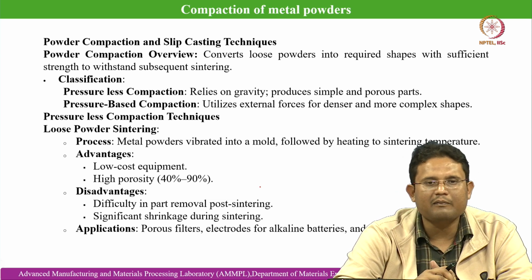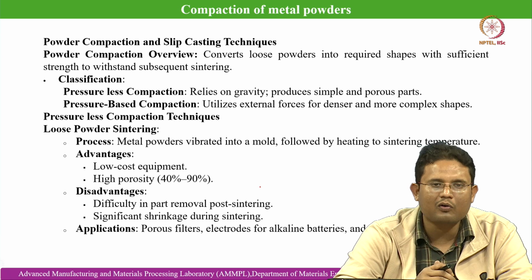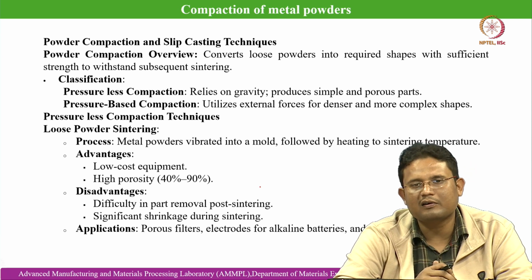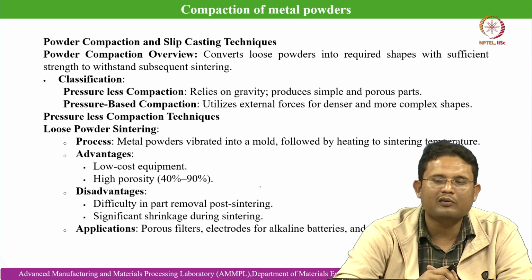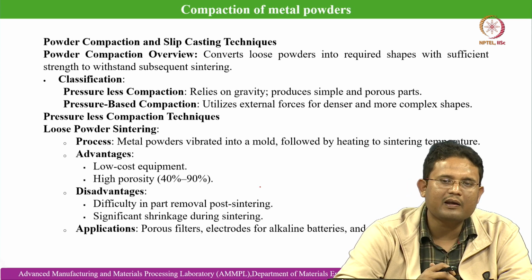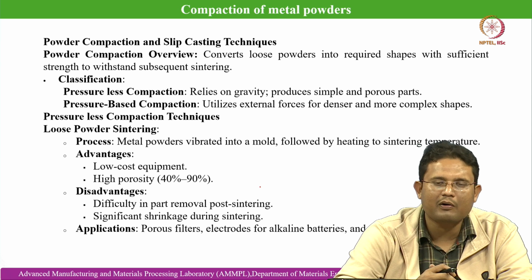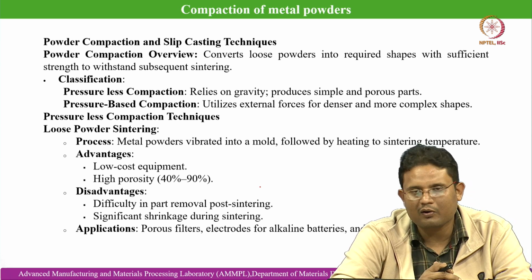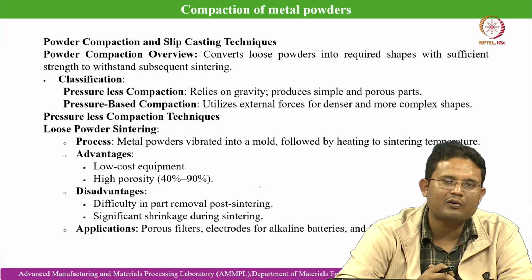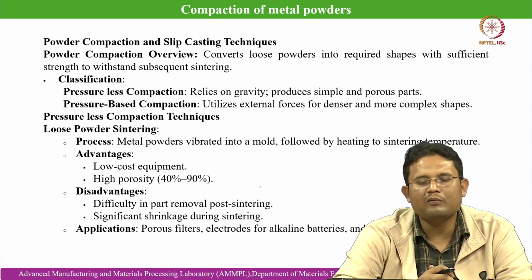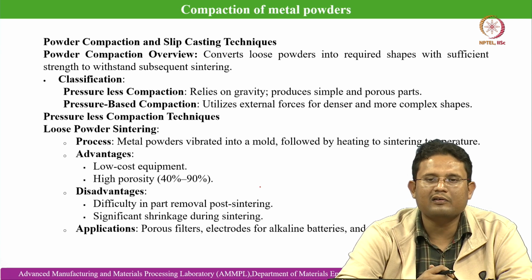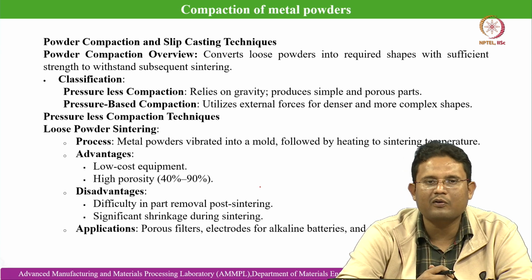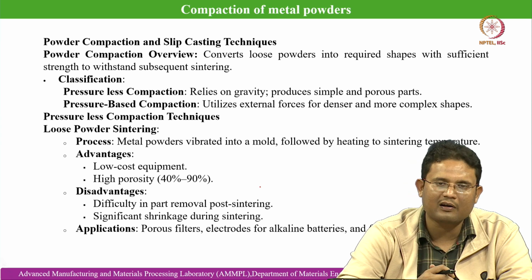The advantages of loose powder sintering are low cost equipment and high porosity. When we are talking about cylindrical porous bearings, then we can go for tap powder sintering or loose powder sintering, where not much pressure is needed, because our end goal is not to get a dense part, rather our end goal is to get a porous object. So that is why we do not try to achieve as high grain density as we can achieve if we go for pressure based compaction techniques.